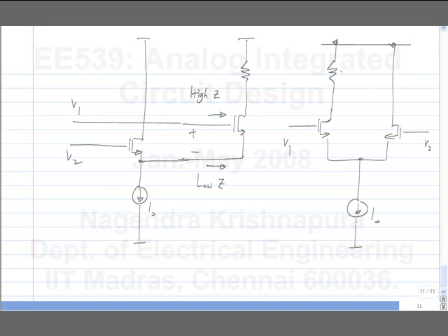What is this? So it's a differential pair. So we already know it, that's why we recognize it, but even if we didn't, perhaps by enough trial and error and reasoning, you would have come to this circuit. Okay. So now we have come up with a circuit which is symmetrical from both the inputs, right? And you can think of it as this transistor being driven at the source by this common drain amplifier.